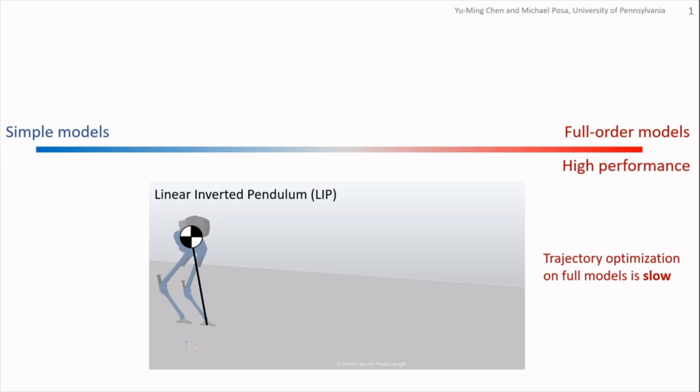They assume that the robot is a point mass, plan a trajectory from this, and then ask the robot to track it with its center of mass. They also plan the footsteps at the same time, then ask the robot to track it with its swing foot. And because of the model's simplicity, these methods can plan desired trajectories in milliseconds.